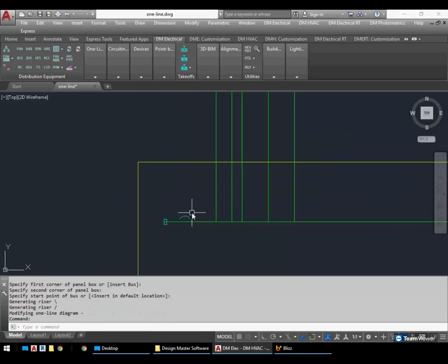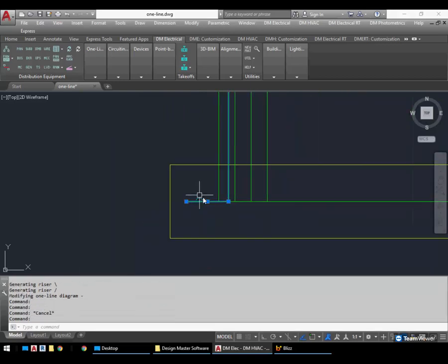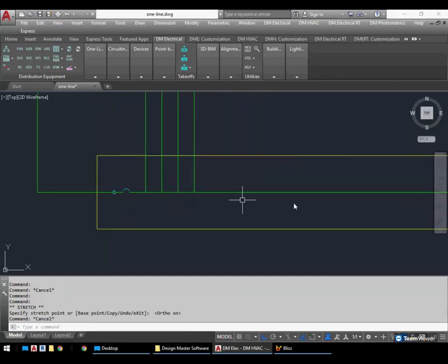You've got just a horizontal bus bar. So the incoming connection connects to the top of it, the horizontal bar and the breaker there, so that's the main breaker, and then all the circuit breakers coming off of it. So those are the options that you have for where the main breaker is placed. That's where it's chosen to be placed depending on your options.